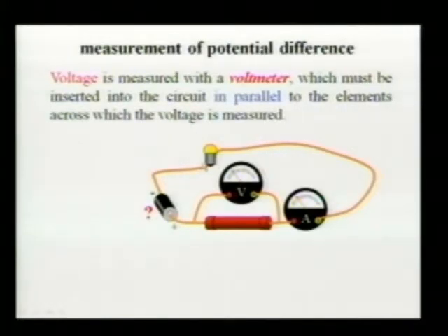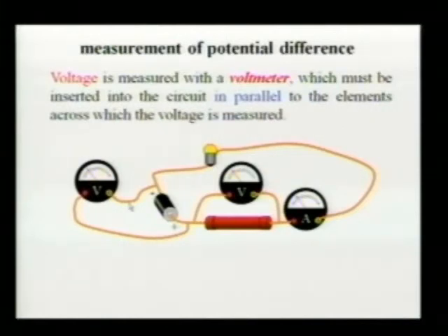It does not measure potential difference across the light bulb either. I can recognize that this potential at the voltmeter is equal to the potential over here by the light bulb, because if the ammeter has 0 potential, you can think about it like a piece of wire. So potential here and potential here are equal. However, this potential here is not equal to the potential there. So these two are not connected in parallel. So in order to measure potential difference across the battery, we would have to connect a separate voltmeter. We could use this voltmeter as well and move it into that location.